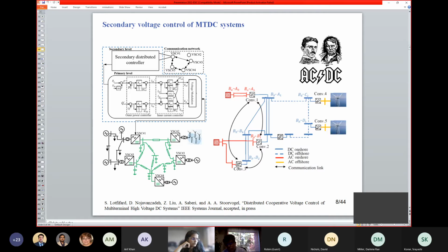These are the 2 main solutions that people are following, because as you said, when a fault happens, you have to have a certain amount of current. If you just go by optimal sizing of the inverter, it's not possible. Yeah, exactly. These are the 2 things that I'm aware of.